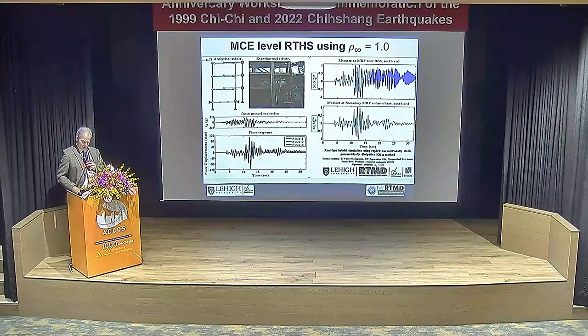Now here's what's important here. If you look at this, and I'll show this more in terms of the applications, this is a 3-story moment resisting frame with a braced frame with dampers. So it's physically defined for the damper system with the braced frame, and then we have the numerical or the analytical substructure, which is a moment frame with RBS connections and the gravity system.